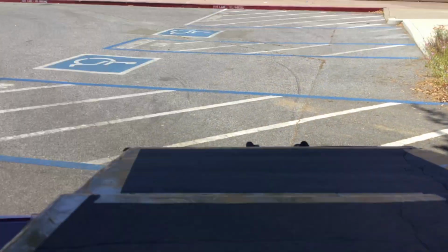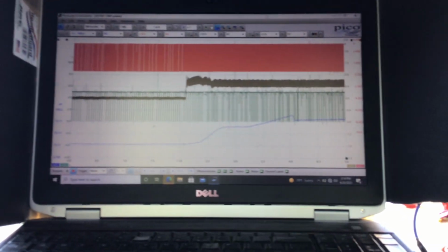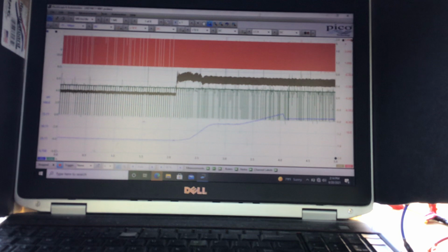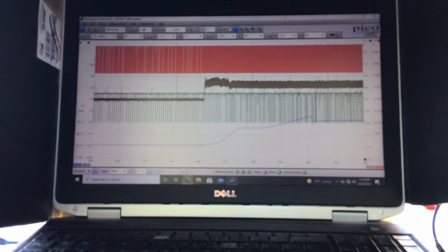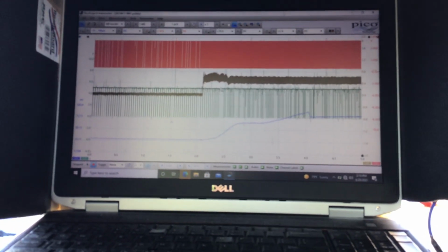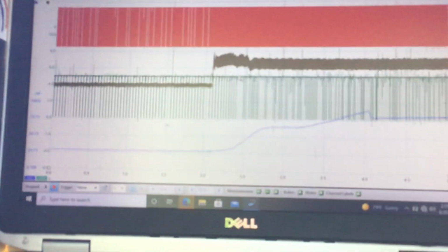As far as our scope, I just want to talk about oil pressure and variable valve timing. It's real important that we check the oil pressure when we have a VVT issue. Now, of course, we wouldn't go to oil pressure immediately. Scan data is powerful. It shows us a lot of things on the PIDs, such as advance, retard, cam position error, things like that. But just be mindful that we want to